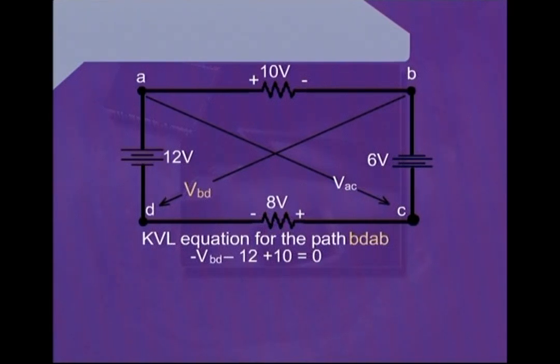After reaching at the point A, we will be facing towards the point B. And also, we can see that there is a resistance between the points A and B. The voltage drop across this resistance has been given as 10 volts, whereas the terminal which is towards the point A has been marked as plus. Therefore, we will write plus and the value of the voltage drop across the resistance, which is 10.